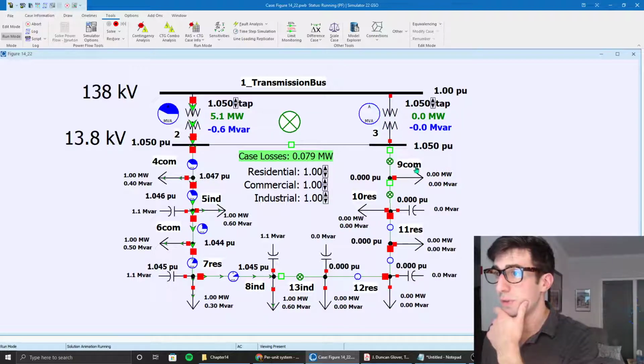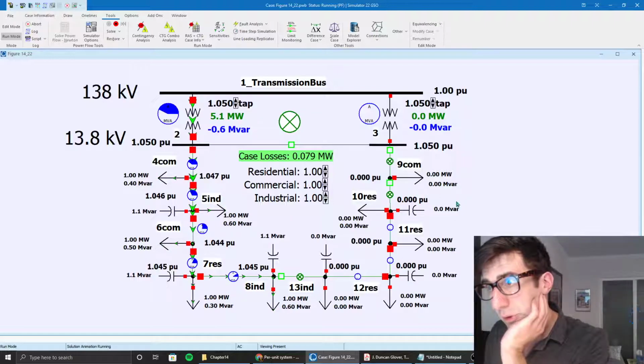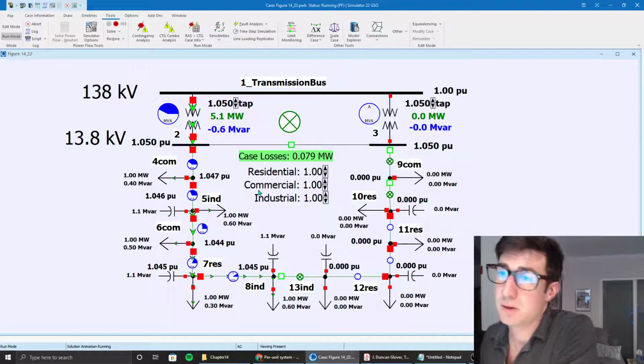So we're going to open these circuit breakers here, and then we realize that we now have 0 per unit voltage going to all these locations, and there is no power being drawn. The end here is the load of the customer. So what we have to do is open this, and we're going to let this transformer take over.